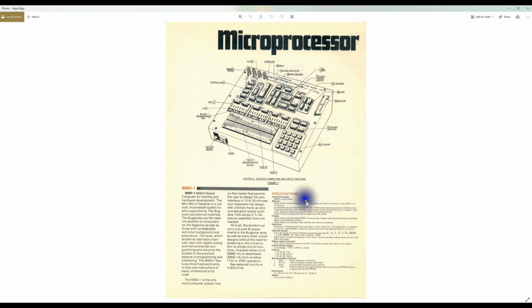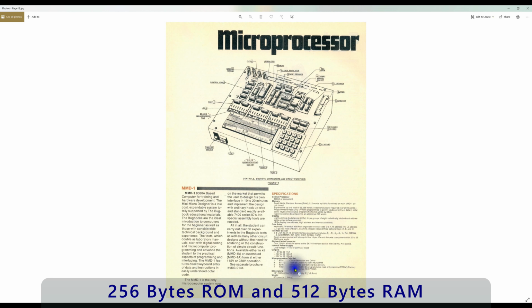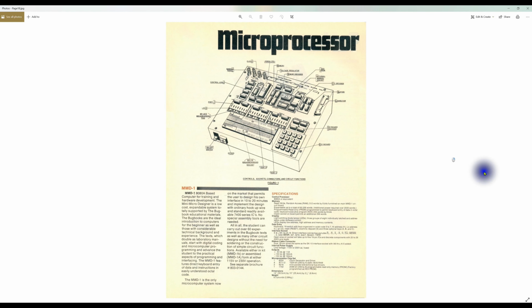8080 processor equivalent. Small amount of RAM, ROM. 8224 clock generator, 8111-2, 256x4 static MOS RAM. So it's an 8111 RAM. There's 4 of them sitting here. I guess to get you 2K. Does it actually have 2K? Interesting. 2048-bit, 256x8 programmable read-only memory. There's 1702 ROMs. There's, in this drawing here, the Hex ROM here.